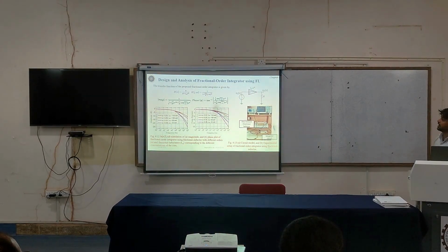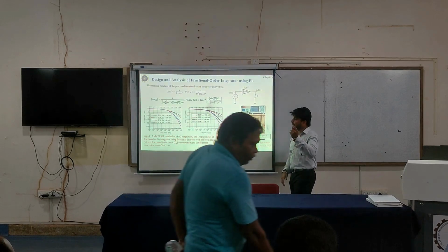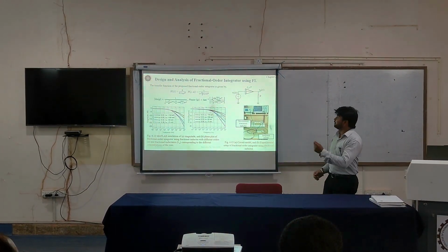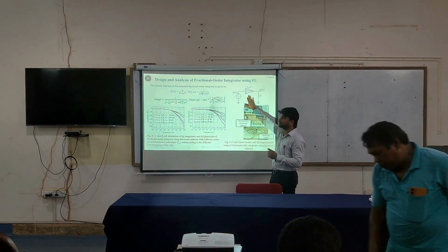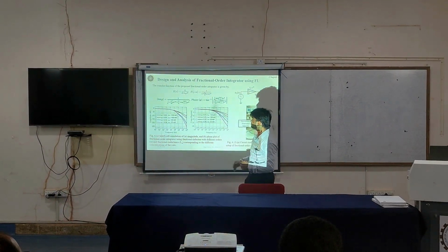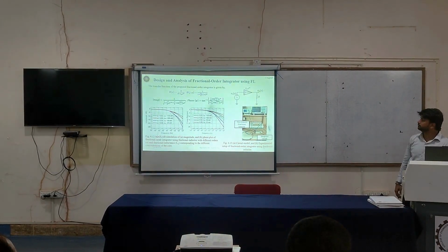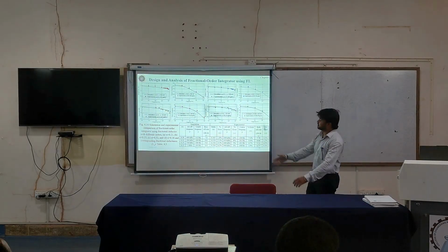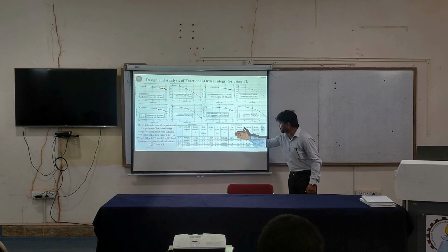Now, design and analysis of an integrator using the fractional inductor. In order to see how this fractional inductor performs, we have used an integrator circuit with a fractional inductor, and these are the frequency domain analyses at different orders obtained at simulation level, then the experimental comparison with the simulated result, and this table shows the simulation results, the experimental results, and their corresponding error percentages.